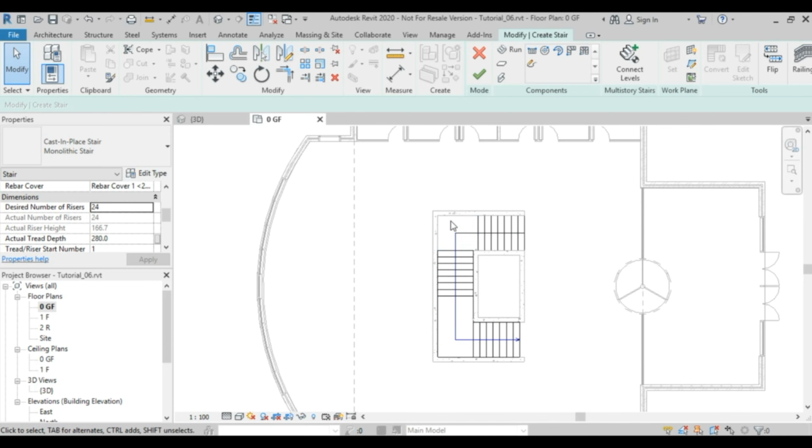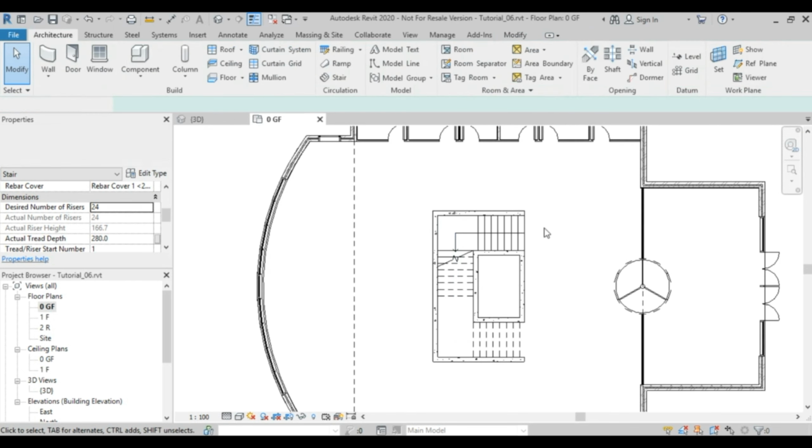You can see now Revit created these 2 for us, which is the first landing and the second landing. Of course, we are putting the staircase and elevator shafts over here, so we cannot manipulate the sizes or even the shapes. And we will say now, as we said, railing is none. We'll say Finish Edit Mode.